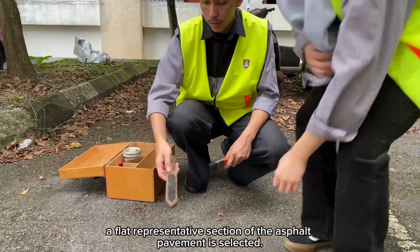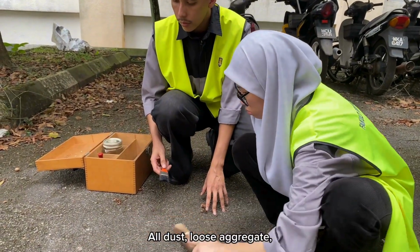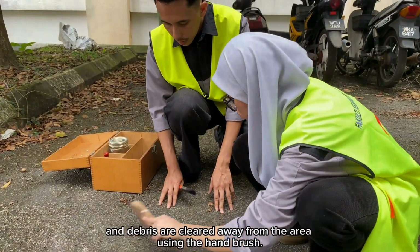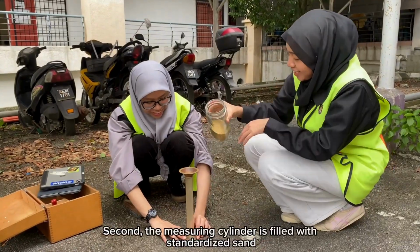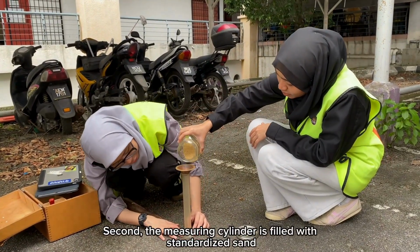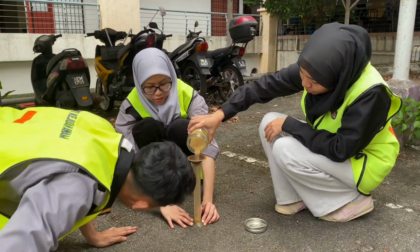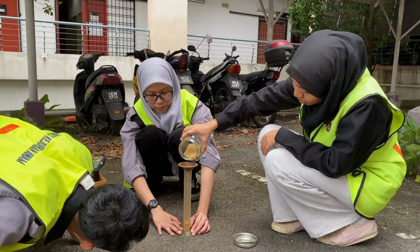First, a flat representative section of the asphalt pavement is selected. All dust, loose aggregate and debris are cleared away from the area using the hand brush. The area is ensured to be completely dry. Second, the measuring cylinder is filled with standardized sand exactly up to the 20 cm cube mark. The top surface is leveled off to ensure an accurate measurement.